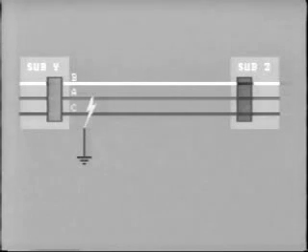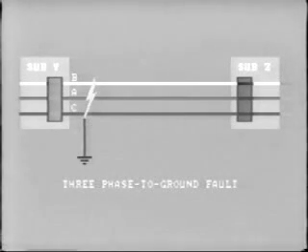At this point, the fault again changes. The A phase conductor now burns open. The tree contacts B phase and falls to the ground. But all 3 open conductors are now in contact with ground, resulting in a three-phase to ground fault. For the next 10 cycles, we have a balanced three-phase fault.